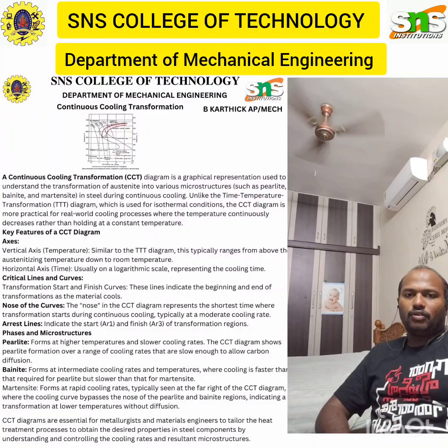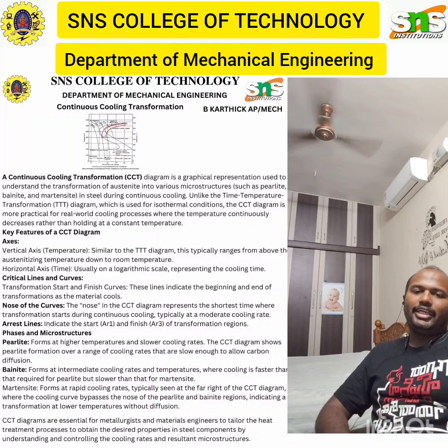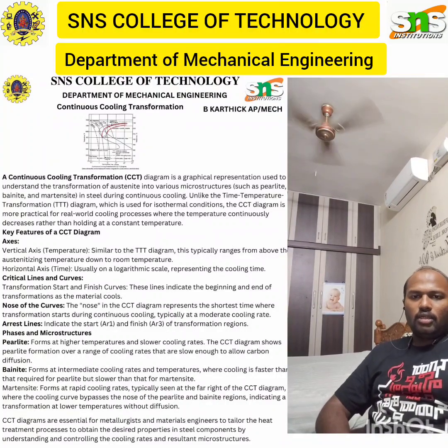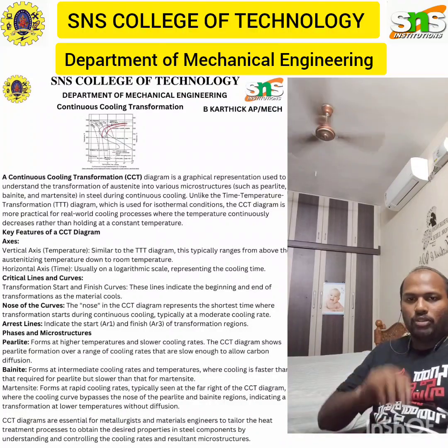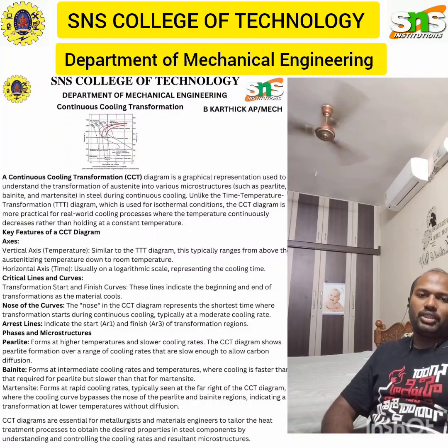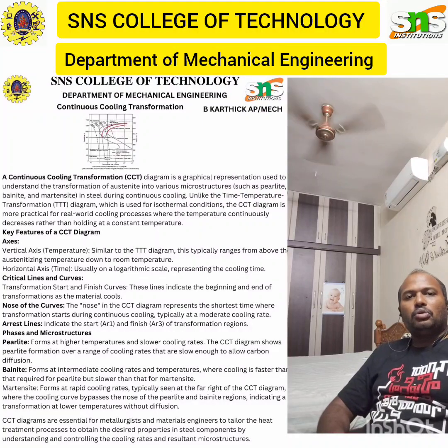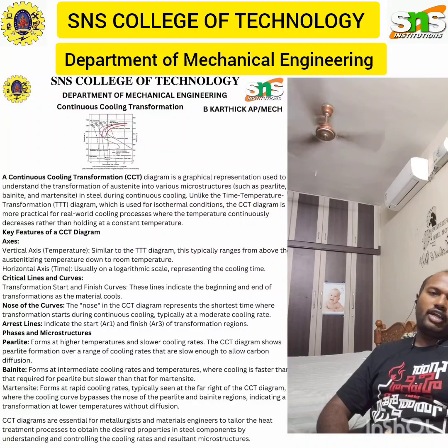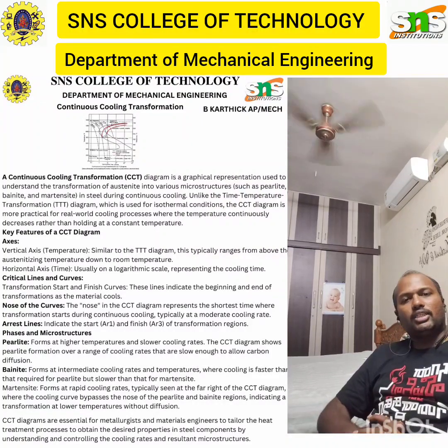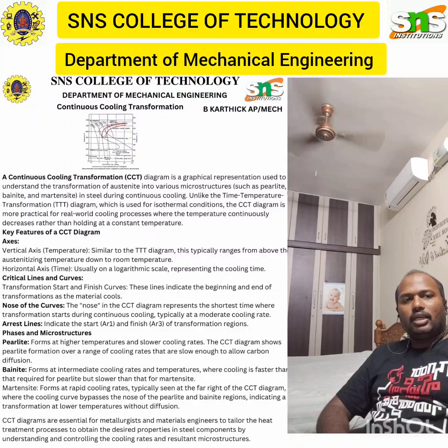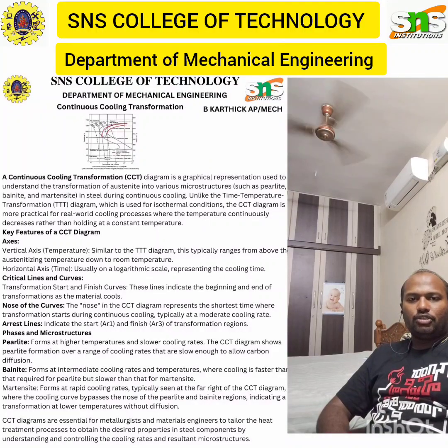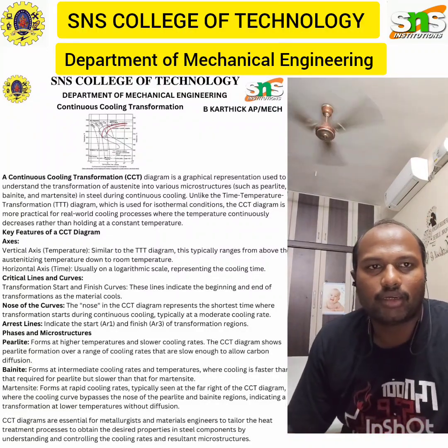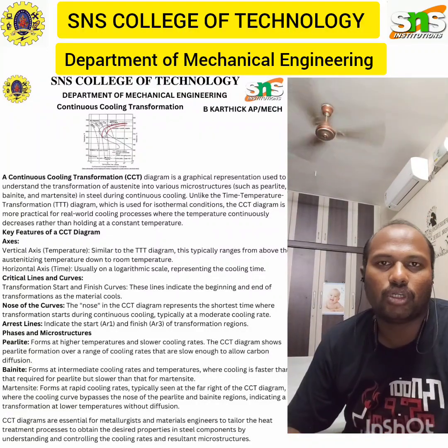In this lecture series for this month, we have seen about different heat treatment processes and the two most important and crucial diagrams which play a vital role in heat treatment process, which is the TTT diagram, time temperature transformation diagram or isothermal diagram. So following that, we are going to see another important graphical representation, which is known as the continuous cooling transformation, which is the CCT diagram, a graphical representation used to understand the transformation of austenite into various microstructures such as pearlite, bainite and martensite in steel during continuous cooling process.